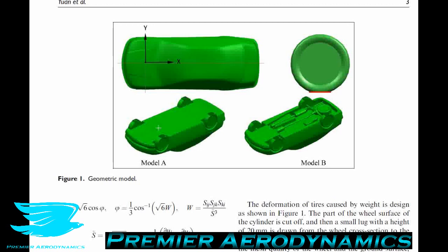Now, in addition to this, the traditional way of making underbodies of cars was to keep them completely exposed. So you have the exhaust, the drivetrain, the spare wheel, even the gas tank, all exposed. That allows the flow to hit a lot more objects, which makes it more turbulent and makes it detach typically, and then the diffuser won't work as well either. So that's the main difference between Model A and Model B, at least that's what is said.